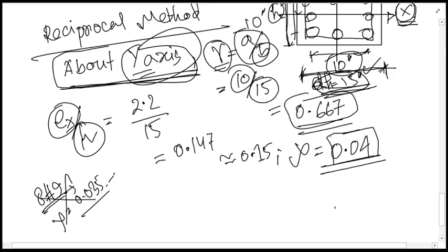We are taking a rounded value for our convenience in this case, but you will be taking the rho value according to your calculation, your particular section's rho, which will be governing the reinforcement which you will be providing. According to that, you will calculate rho as the area you are providing divided by BH. This will be your reinforcement ratio.